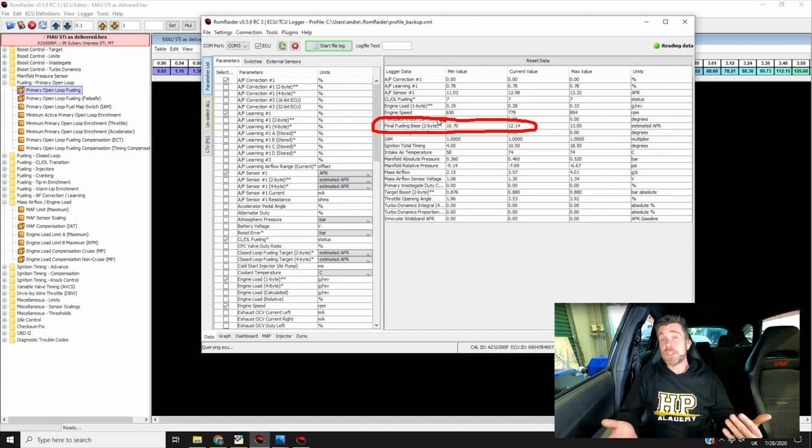So this is essentially the commanded air fuel ratio. It comes from the open loop table that we just looked at there. When we are in open loop or under closed loop conditions, generally 14.7 to 1, of course, our stoichiometric air fuel ratio. So the reason we need to log this is that between looking at our measured air fuel ratio